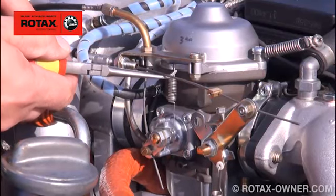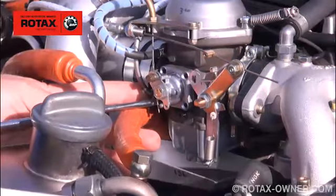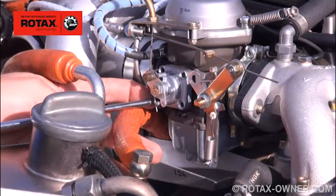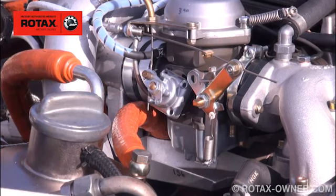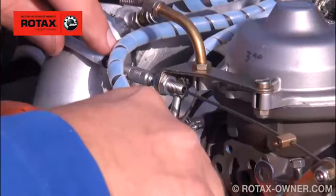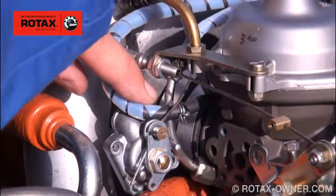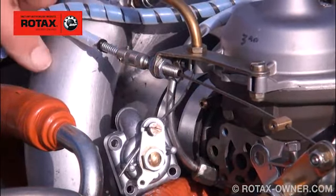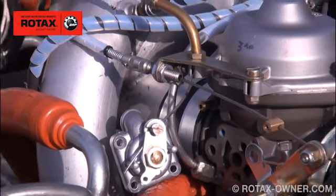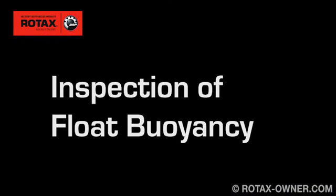Remove the choke lever return spring. Remove the 4 Phillips screws holding the choke valve housing on with the gasket. Remove the carb air vent overflow line. The installed hard steel, or on some models the soft rubber, fuel supply line must not be removed. Now you are ready to perform the test procedure.